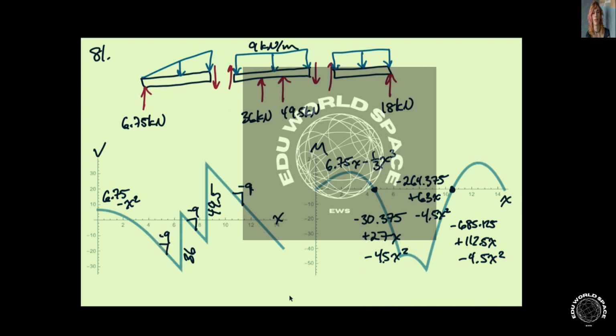If we take the integral of minus 9x, we get minus 4.5x squared, which confirms that. Then there's a constant in this function, which would be 27. We determine this constant of integration by making sure that this function at x equals 4.5 meters is 0.